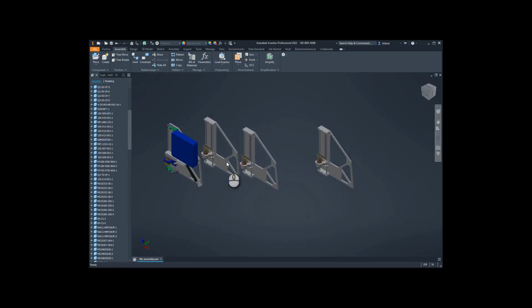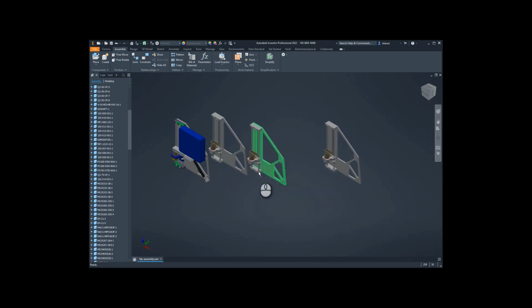So what we can do is create a little bit of structure, or create objects that you can choose or make invisible or suppress, and things like that, by the use of folders. I'm going to start off with how to create a folder. One of the things you can do is click on the assembly at the top, and you can see the option to create a new folder. Give it a name. I'm just going to rename it folder 1.